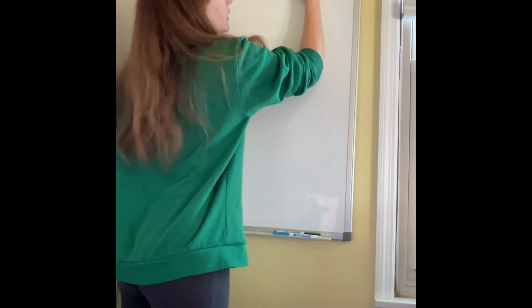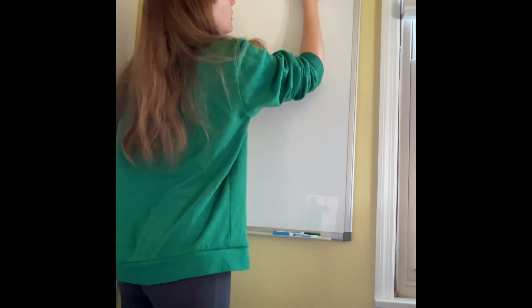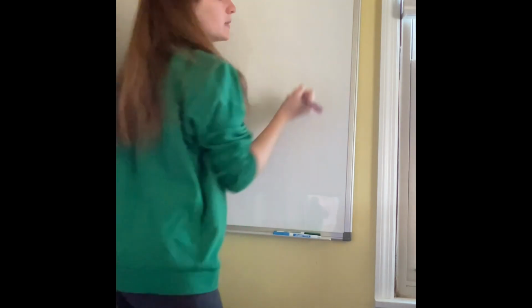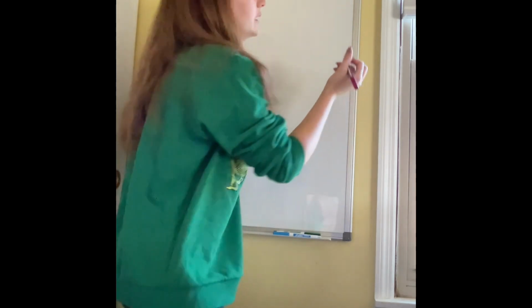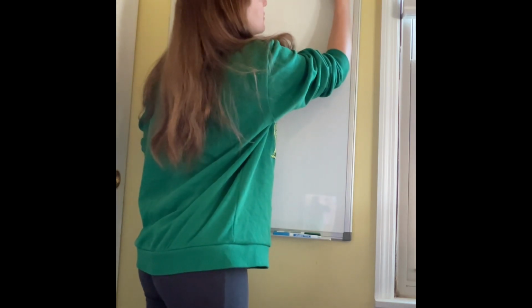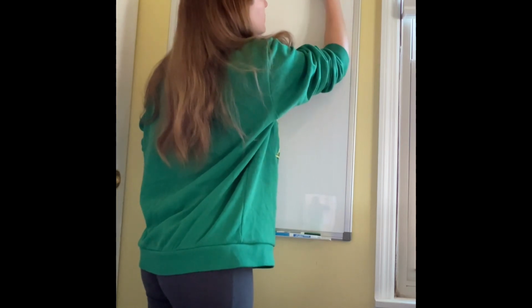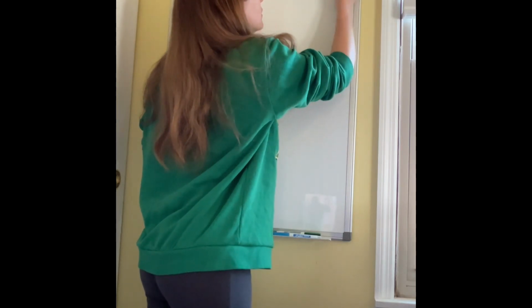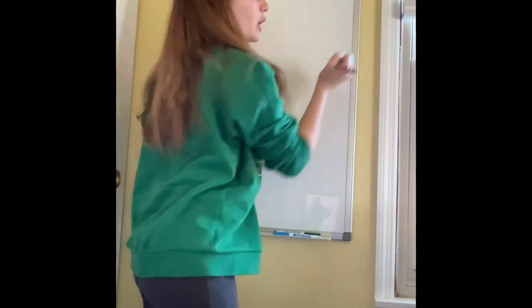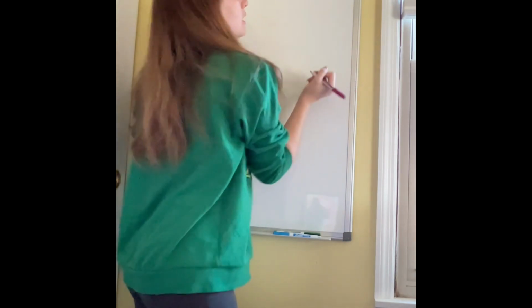We go through another transfer function of 1 over R1, which outputs our Q2. Then we go through our second tank, which is A2 R2 S plus 1 in the denominator over R2. This tank outputs the variable we're looking at, H2.